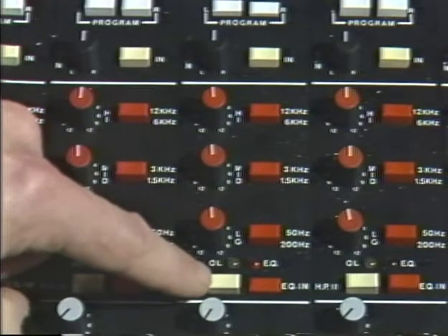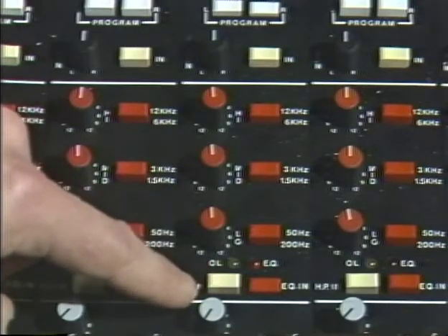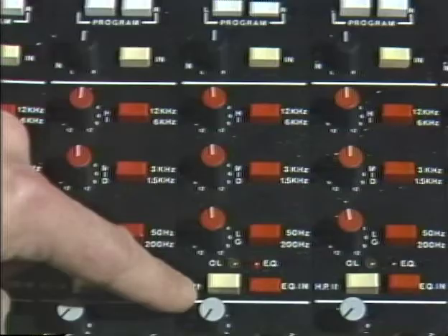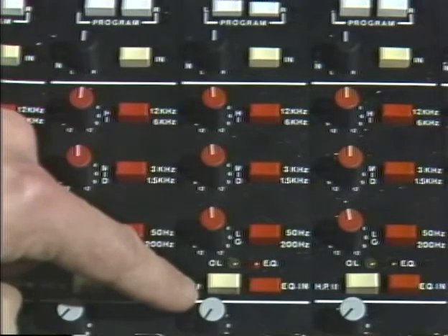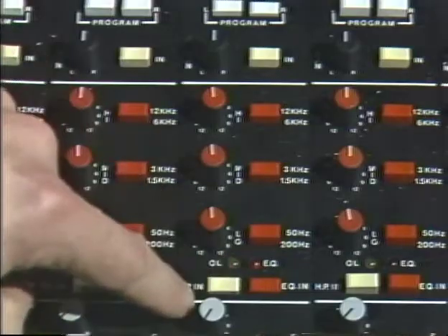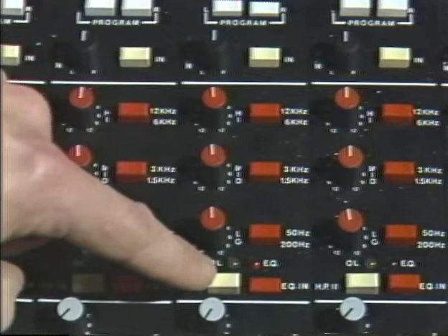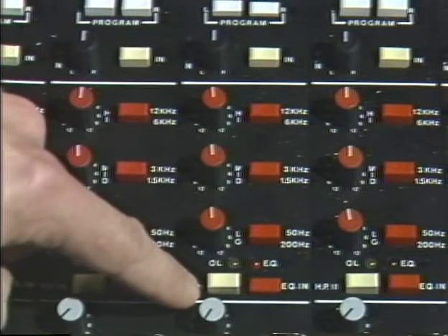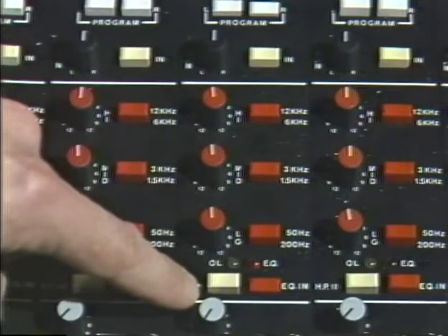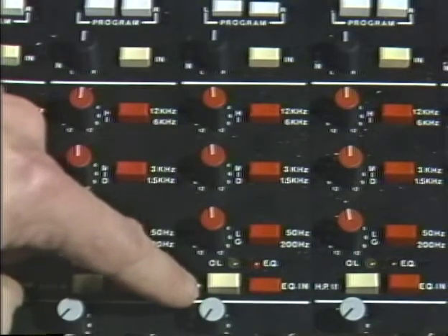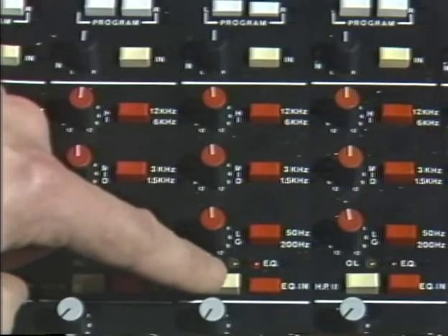which is this white switch. And this switch is a high-pass filter that essentially cuts out frequencies below about 100 cycles. So what it means is that if I put this switch in, everything is more or less flat above 100 cycles. And what that's used for basically is to eliminate perhaps 60 cycle noise if that's present, or some low frequency hum or whatever. Well, we won't really demonstrate anything with that.